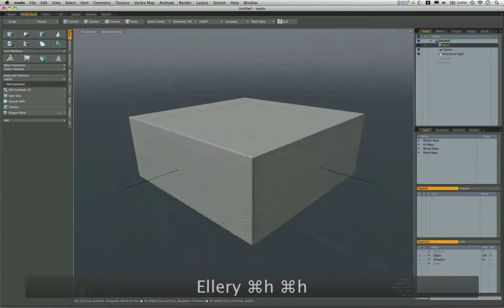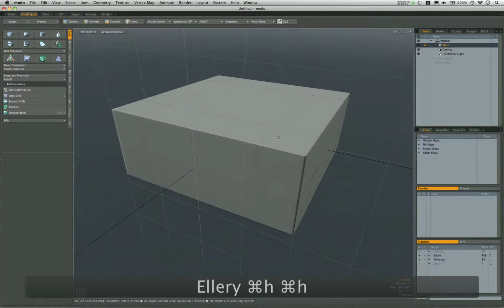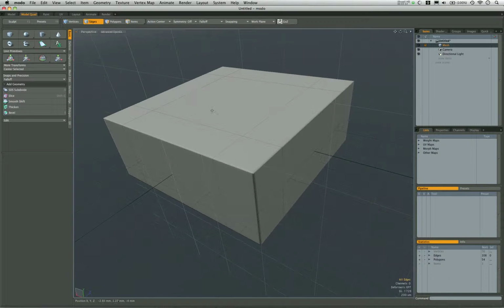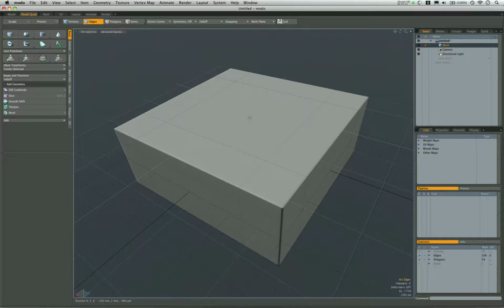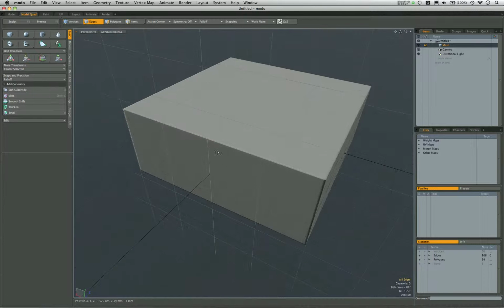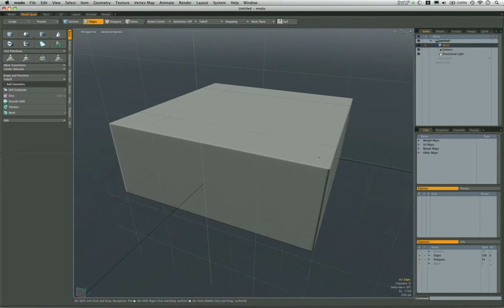Okay, so there are a couple of ways that we can add something circular onto here. And using subdivision surfaces, remember that anything with even sides is going to come out circular. However, we do want to define that circle in order to make it look good and convincing. So we can just bevel off of this in one piece to get a circular surface, but we can also divide up this cube and give us a more appropriate bridge point to attach a circular surface for the top here. Now there are a number of ways that you can divide this up.